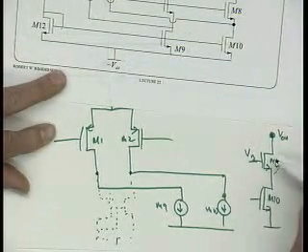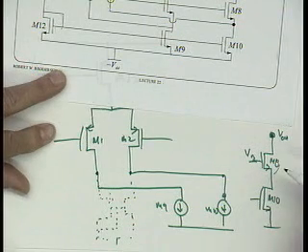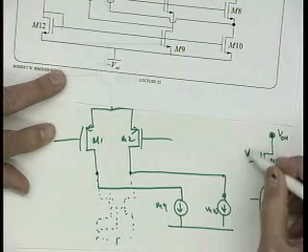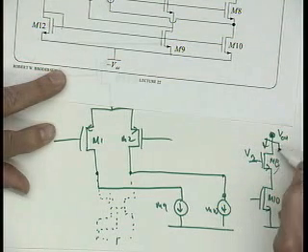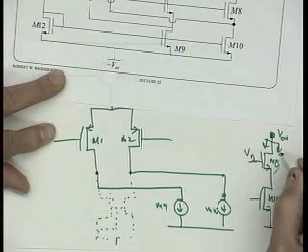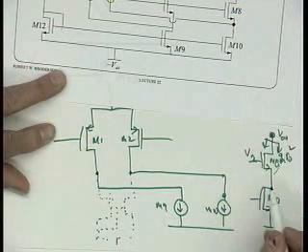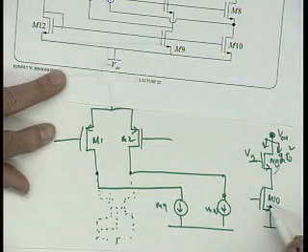So what is it acting as? What's the other name for it? Cascode, right? That's exactly what a cascode is. This guy's acting like a cascode for this M10. So looking down to here, what's the output resistance I see? I see good old gm r0 squared looking down into this lead. So M8 is just a cascode of M10.